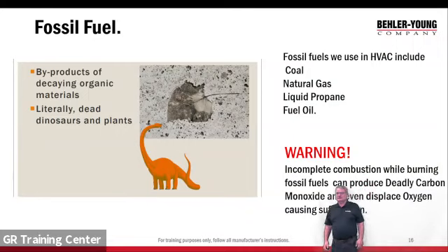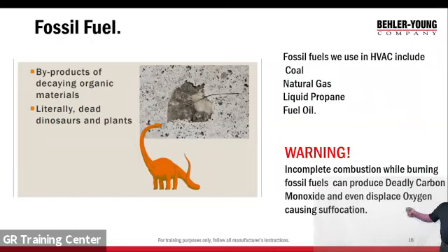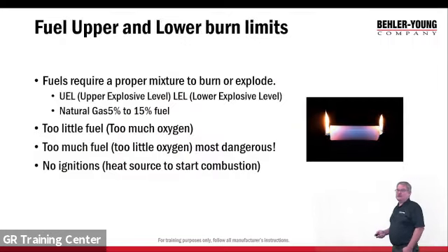With carbon-based fuels or fossil fuels, we want to heed this warning here. Incomplete combustion while burning fossil fuels can produce deadly carbon monoxide and even displace oxygen, causing suffocation. This is a concern with any of the fuels we're dealing with. Number one is incomplete combustion producing carbon monoxide, which is deadly. We'll talk about that a little bit more. And then we can also displace the oxygen because the fire uses the oxygen. If we use up all the oxygen and you walk in, obviously you can suffocate. So this is a big warning. We'll talk about it a little more as we go.